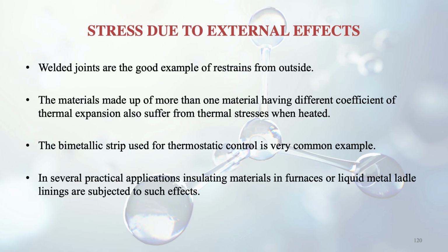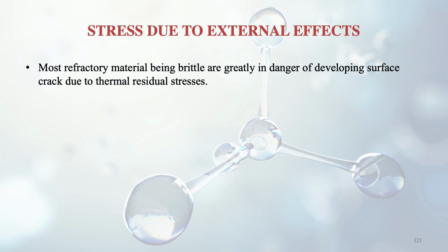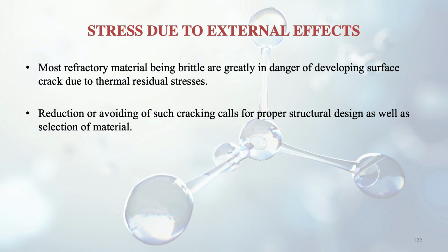In several practical applications, insulating materials in furnaces or liquid metal ladle linings are also subjected to such effects. Most refractory materials, being brittle, are greatly in danger of developing surface cracks due to thermal residual stresses. So refractory materials are generally brittle, so obviously thermal stresses will come in. Then reduction or avoidance of these cracks is very much needed, and for that we need proper structural design as well as selection of the material.